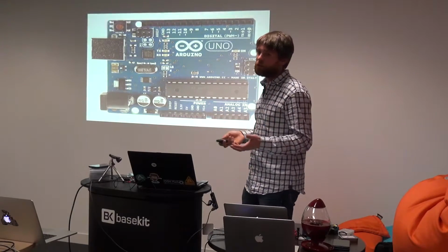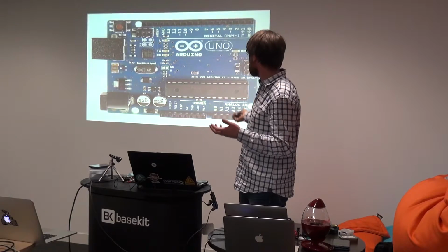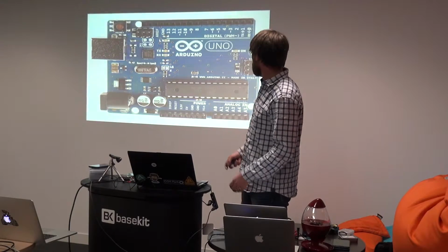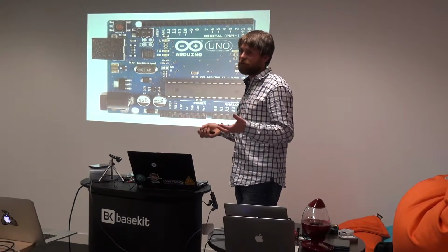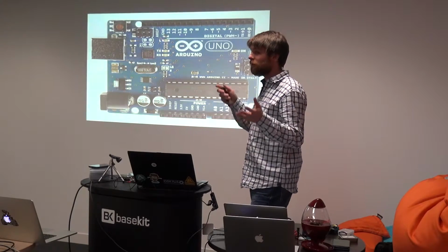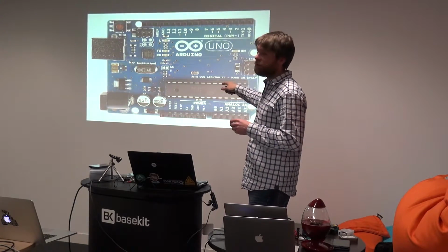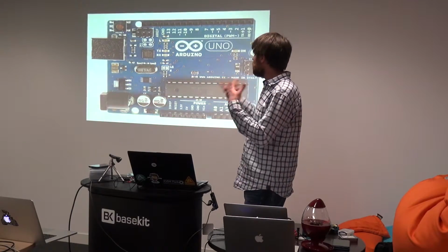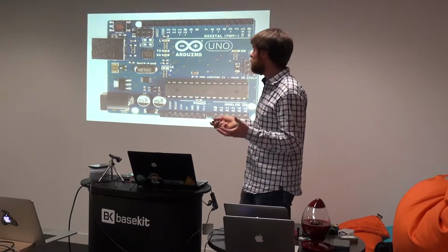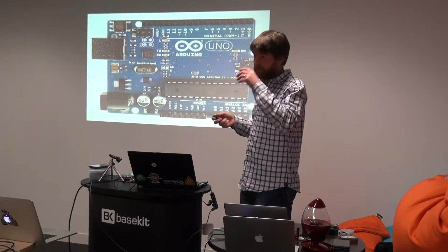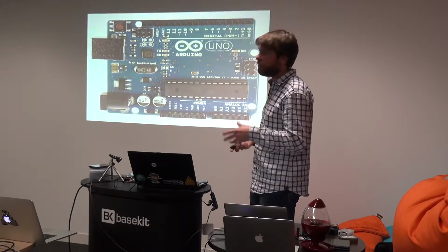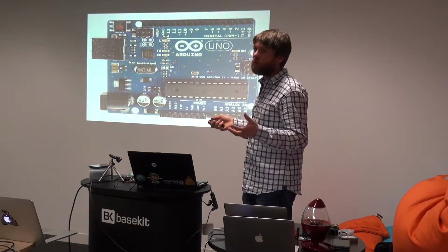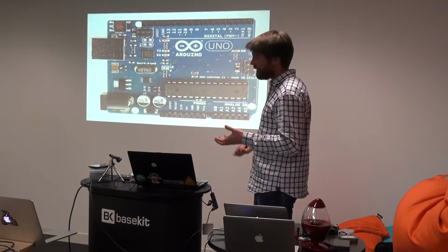And for most people, it's an Arduino. So you've got this, which has got a little USB interface on it there, and then the actual microcontroller here. If you want to turn a light on from your computer with it, you've got to put a bit of software on there that will interpret signals from your computer. You've got to write code on your computer to send the signals, and you've got to have established a protocol to do it. At the moment there's Firmata, which does a whole bunch of different stuff like that, and it's used by Johnny-Five and other things that you might have heard of. But it is a bit long-winded, and actually understanding how everything works is really painful.